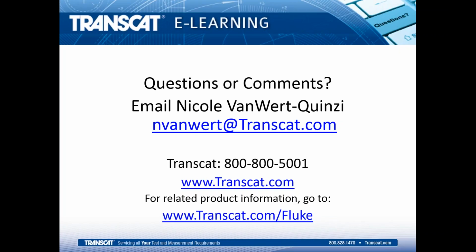You just connect your switch up to the terminals, and when you take it above the switch point and down below, it'll trigger the dry block to record the reading so that you can calculate the deadband afterwards. In the case of the field metrology wells and the metrology wells, there's actually an automated program for that. So you connect the switch and run the automated program, and it will actually calculate the deadband for you.